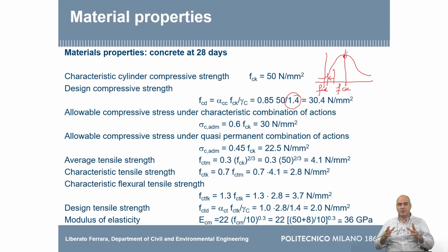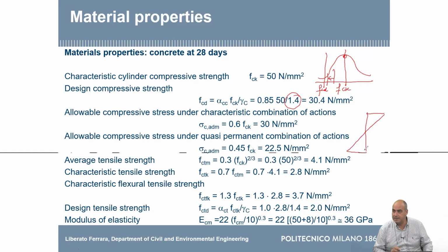in our structural elements, are we really experiencing direct tensile forces? Well, we could have some ties, concrete ties, but where we generally do experience tensile stress is because we have a bending action. And in a bending action, the distribution of stresses over the cross section is like this. You have compression stresses here, sigma c, and you have tensile stresses here, which we call sigma ct.